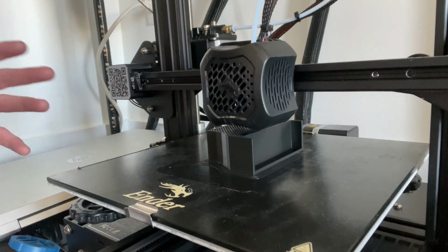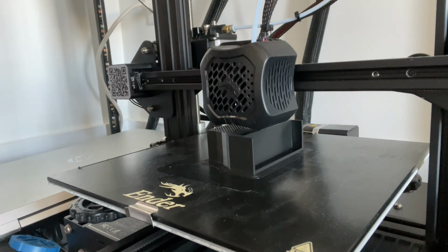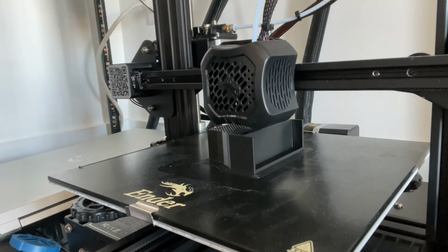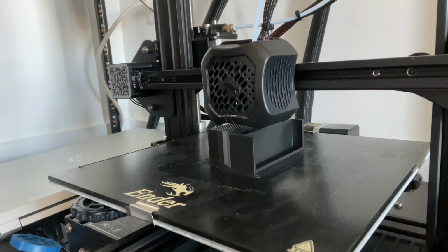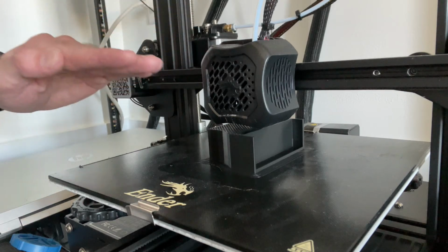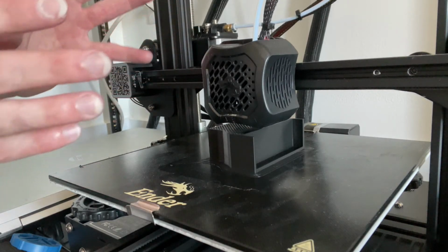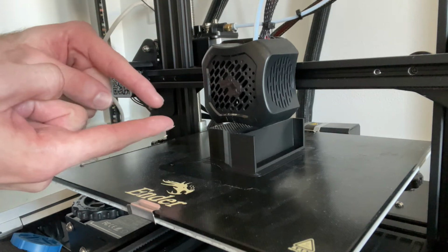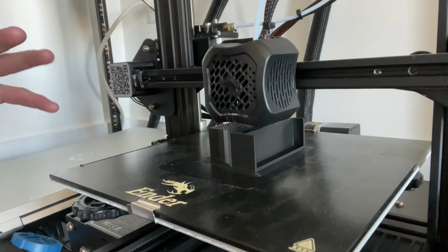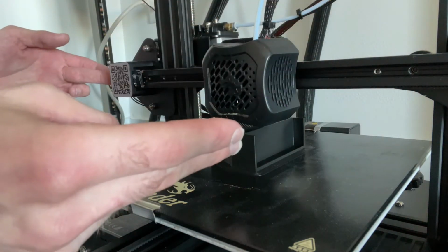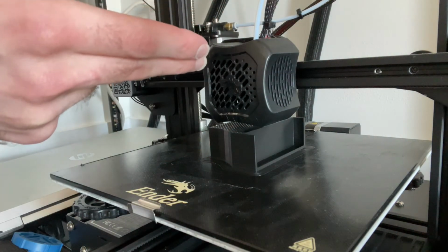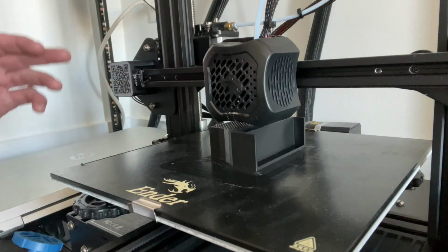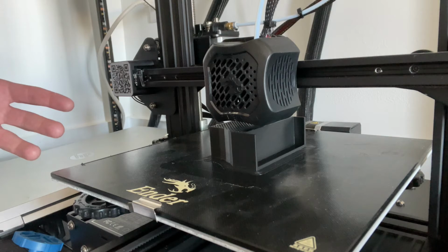Since I am controlling the 3D printer with FIFO pipes in Linux, I should be able to check the logs of my print. I'll show you the script in a second to show you how I'm going to do this, but I should be able to find exactly which gcode command led to this state. So exactly the XYZ position of the extruder right now should be available in the logs. From there, I should be able to just move the Z axis up about 10 millimeters to give it some space. I will be able to heat up the hotbed and the extruder back to their operational temperatures.